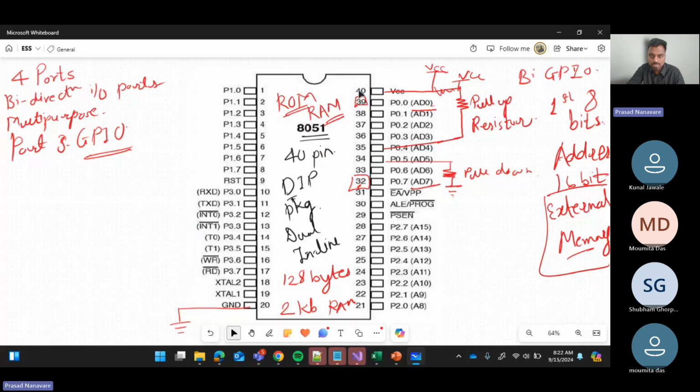Okay, 32 to 39. इसमें 8 pins हैं, and these 8 pins are externally pulled up. Okay, these are not internally pulled up. Pull up is basic: when I say pull up, externally register connect किया है VCC को, pull down means वही register ground को connected किया है, ठीक है? सो ये है पुल अप पुल डाउन का थिंग, उस पर ज्यादा ध्यान नहीं दिया तो भी चलेगा.